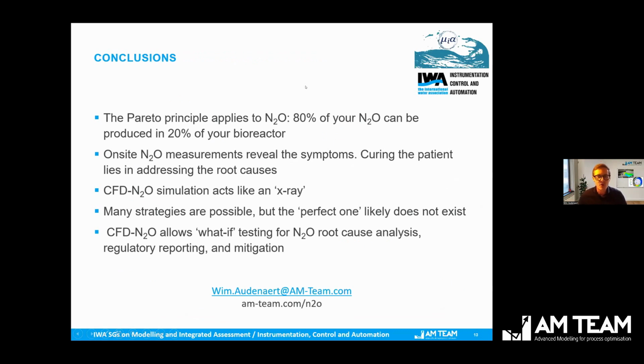So this brings us to the conclusions of this slideshow. We believe that the Pareto principle applies to N2O: 80% of your N2O might be produced in only 20%, or even less, of your bioreactor volume. So it's about understanding the production volumes. We also believe that N2O measurements reveal symptoms. They give you an idea of how bad it can be or what the variation can be. But to really cure the patient, you need to address the root causes.